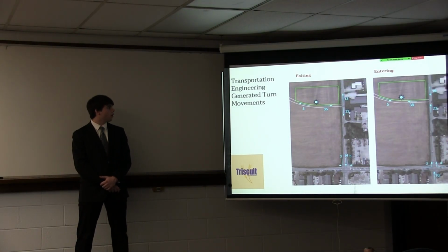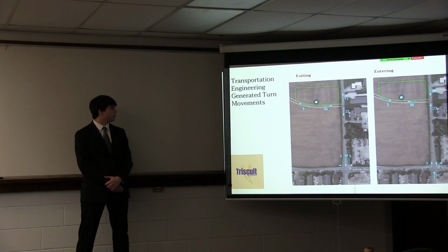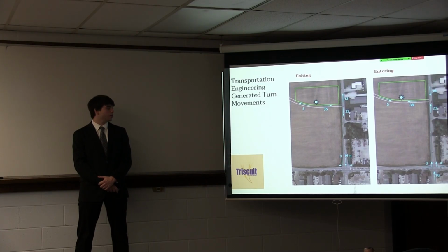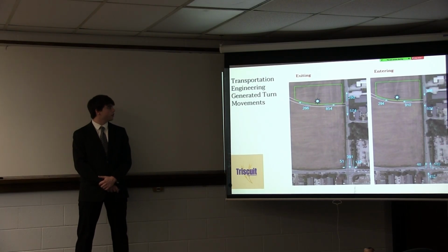So for just our parcel, I generated some turn movement predictions. You can see that a lot of the turn movements will be going through the intersection at East Summit Street and North Indiana Avenue, and less towards the Maryville Road side. And then here it is adapted to all of the parcels that will be created. Just some predictions. You can see a lot going through the through street at the intersection, which is a common theme.